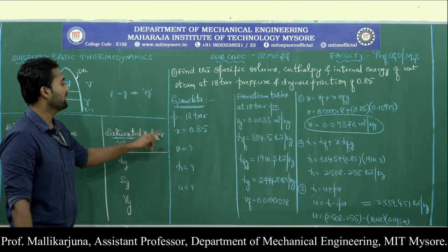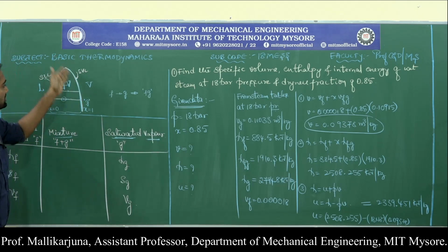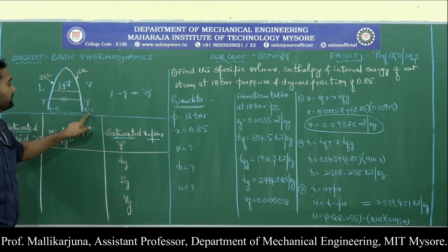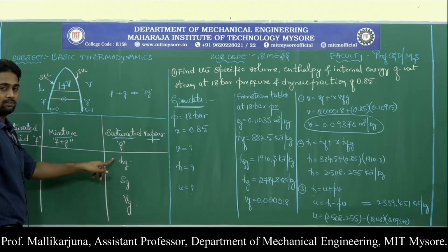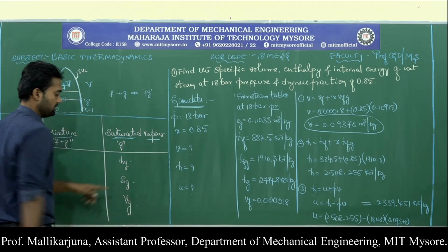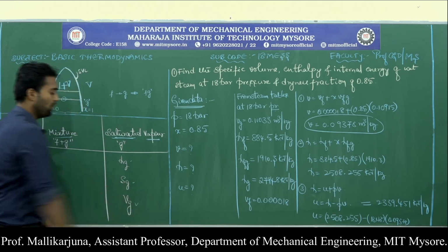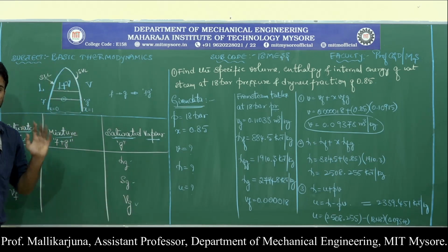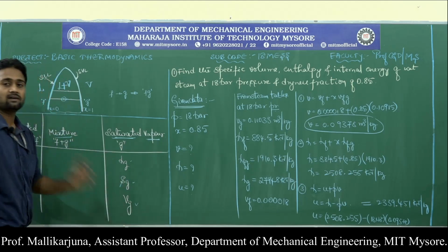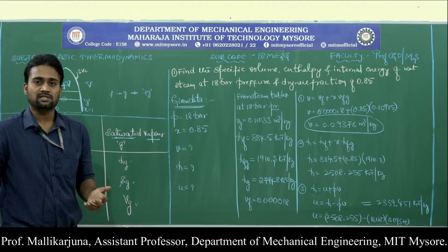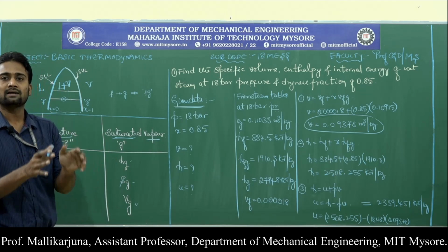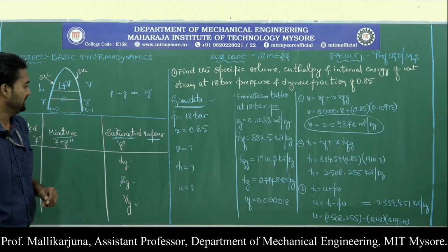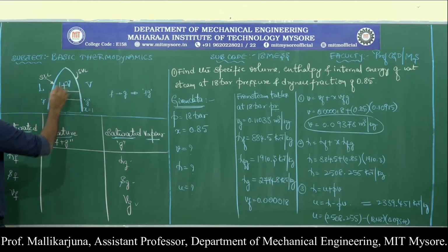And look at the saturated vapor. The saturated vapor line is this, and whatever we write as a property on this line will be denoted with the help of g: specific enthalpy of the saturated vapor, specific entropy of saturated vapor, specific volume of saturated vapor. So, these are the notations. Make sure all of them are small letters, because of that I am calling it specific. Specific in the sense all those properties are expressed with respect to unit mass, wherein the mass of the substance is unity, 1 kg.